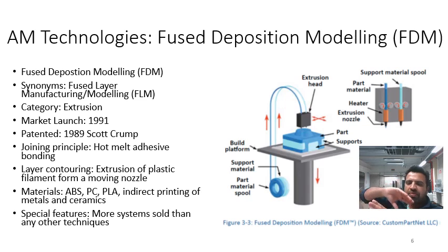When that filament is extruded into a part, this part contains polymer contents and also metallic or ceramic contents. Polymer contents are removed by heating to a higher temperature or dissolving in a soluble solvent, and in the next stage, the part is fired to a higher temperature to increase the density of the part.